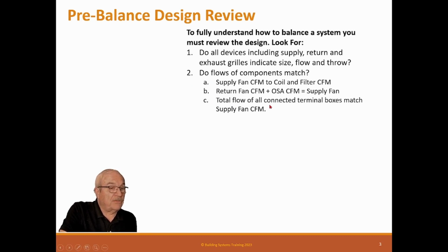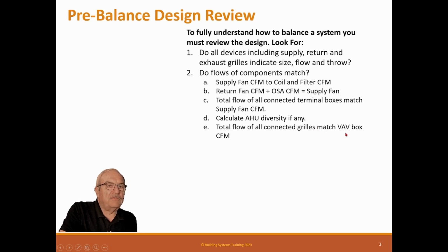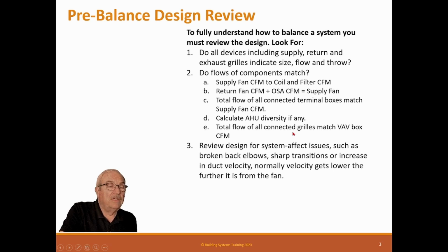If they do, that's great. Then you have a normal VAV system. If not, then you have diversity. Calculate air handler diversity, and that is if you have more CFM in the VAV boxes than you do in the air handler, that is diversity. Does the total flow of all connected grills match the VAV box CFM? Do the grills connected to the box match the VAV box? They need to. If not, there's something wrong.